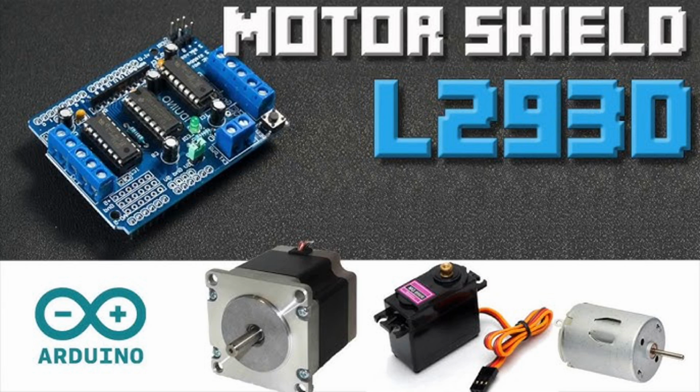Summary of key features. PWM control, the basic form of control, where the motor's position is determined by varying the pulse width. Feedback control. Closed-loop systems provide real-time position and speed feedback for high accuracy and stability. Motor type. Servo drivers can be designed for different types of motors, including AC, BLDC, and DC motors. Programmability. Some drivers allow users to program motion profiles, speeds, and other parameters for more customized behavior. Integration. Integrated servo systems combine the motor and driver into a single unit for ease of use and compact design.